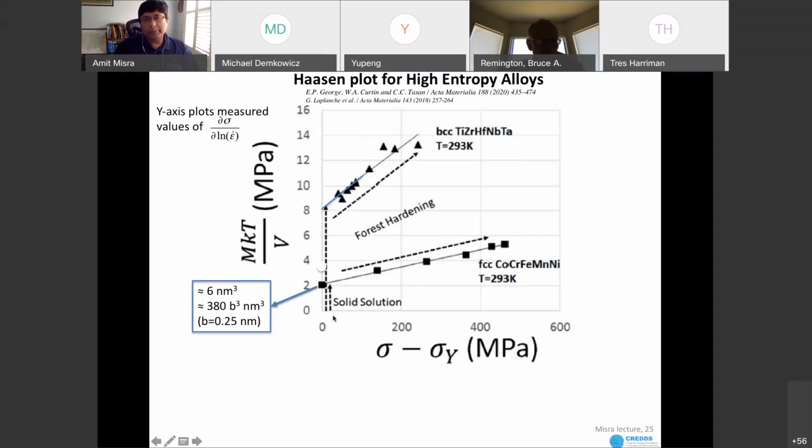And so from this, the authors were able to argue that the high entropy alloys do not show any different kinds of mechanisms. You would get a similar kind of number if you had solid solution FCC alloys, which means fundamentally that it doesn't change into a different order of magnitude. It is the same type of mechanisms, it's just the magnitudes might be a little different.